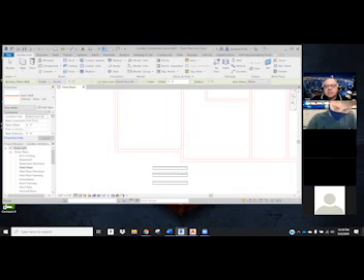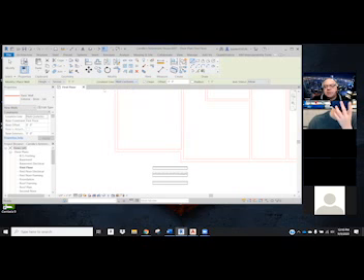I want you to move across to Location Line. And right now yours probably says Wall Centerline. That's usually the default. That's to make it really, really hard for you to draw your wall precisely and to get exactly what you want. Okay.